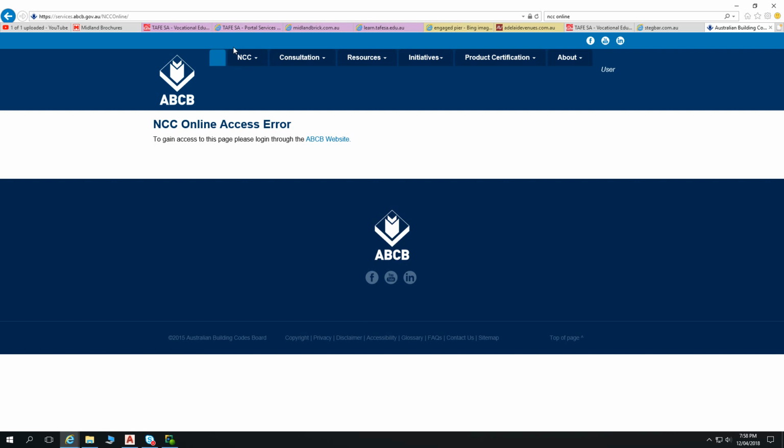But I do expect you to say the use of this system increases our floor depth. That might mean a lower ceiling, or it might mean a higher ridge height in our roof. That has to be accommodated for. And with a higher ridge height in our roof, there may be some issues in regards to council approval. Yeah, that's a good thing to have. Some possible answers there. But you don't have to get too specific about the construction of that.